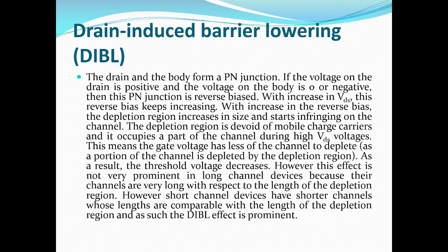This means that the gate voltage has less of the channel to deplete. That means a portion of the channel is depleted by the depletion region. As a result, the threshold voltage decreases. However, this effect is not very prominent in long channel devices because their channels are very long with respect to the length of the depletion region.